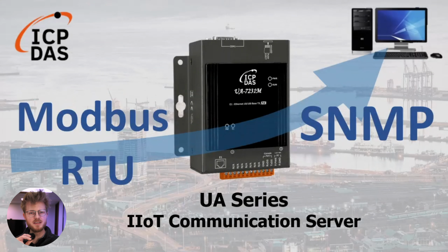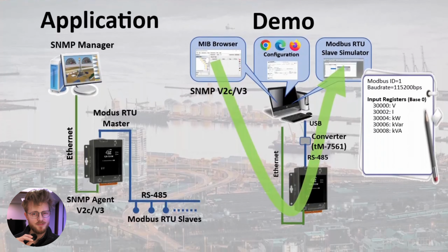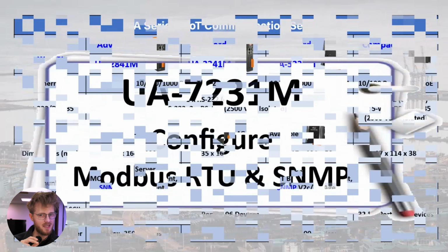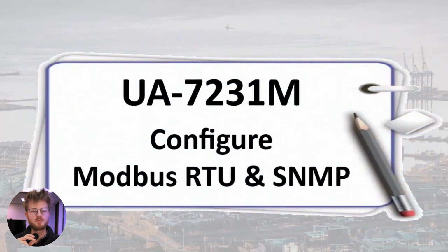If you need to convert Modbus RTU data into SNMP for network-based monitoring systems, the UA series provides a straightforward way to do that. In this video, I'll be walking you through the UA series configuration step by step, showing exactly where to go, what to configure, and how each setting fits into the overall setup, so you can follow along and apply this to your own system.